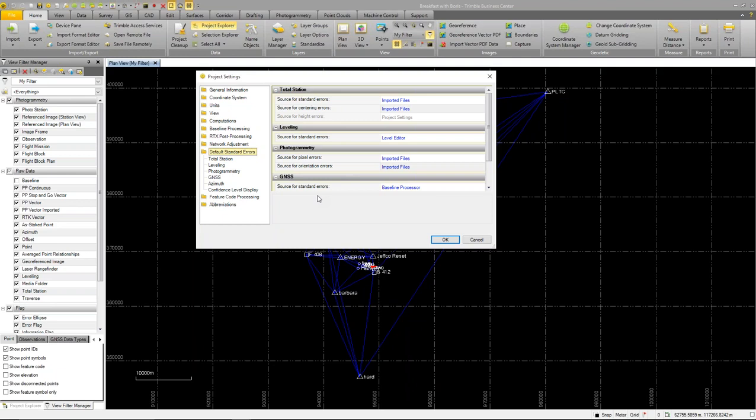Okay. Okay, go ahead, Boris. Andrew's question was, when you do a network adjustment and include deflections, rotation, and scaling, does that create a local site? So maybe if you can just clarify both. Okay. So you'll see a set of transformation parameters for this network generated from fixing your observations to the control. Later on, I'll show you a little bit of that.